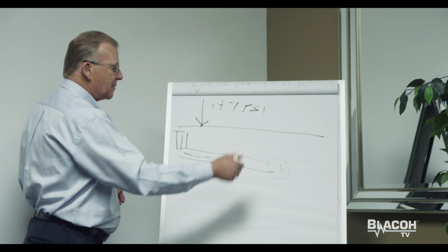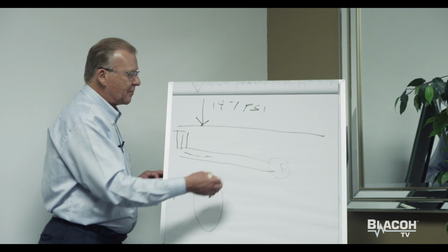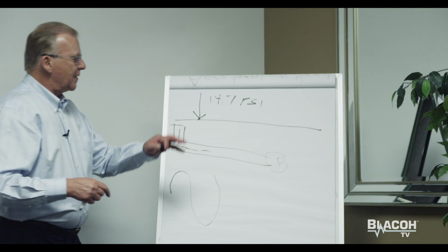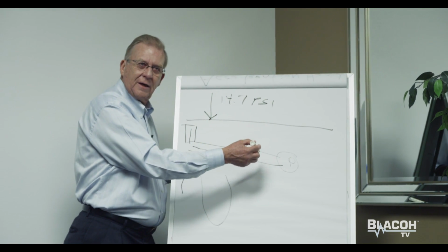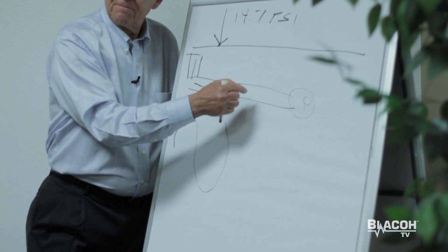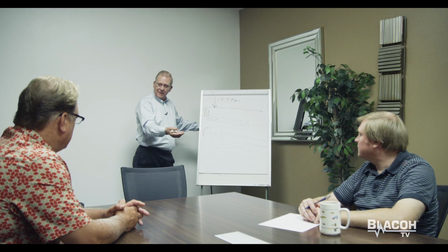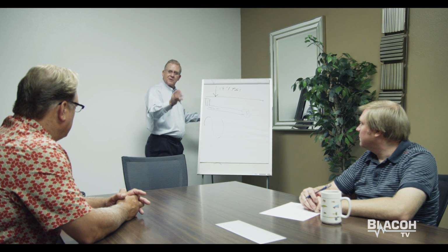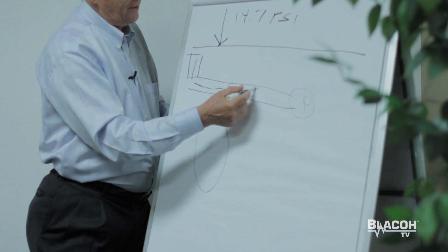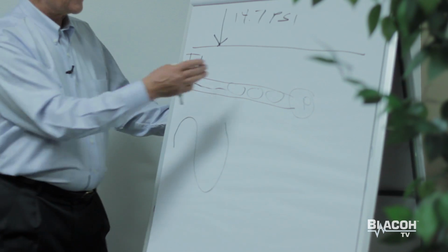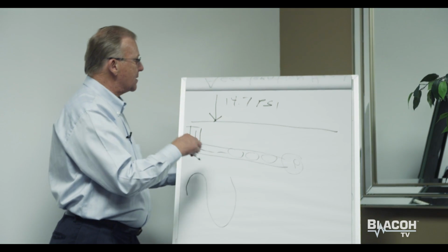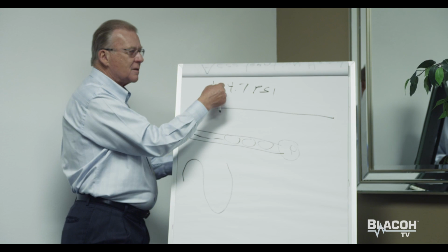In other words, every time this pump shifts, remember our sine curve, not only does the flow slow down on the discharge side, but the inlet valves close and the flow slows down and stops, depending on the number of pistons in the pump, on the inlet side. Now, you've got to re-accelerate that flow, right? On the discharge side, we're pushing it with energy, but now we've got to restart that flow. In a loose sense of the word, it's coming in slugs. Well, if you have a lot of friction loss, you're going to lose flow because, remember, we've only got this 14.7 pounds.